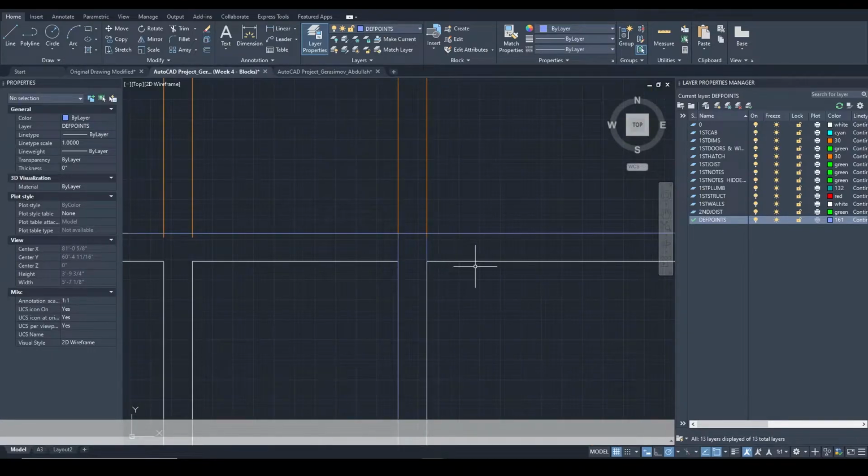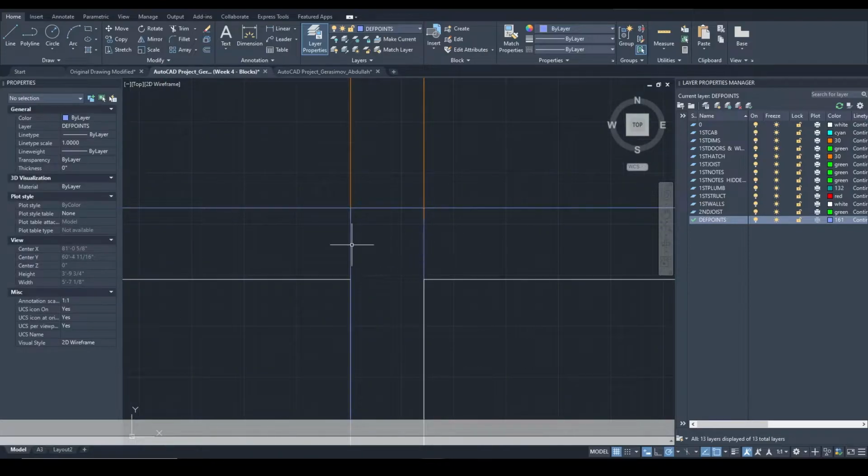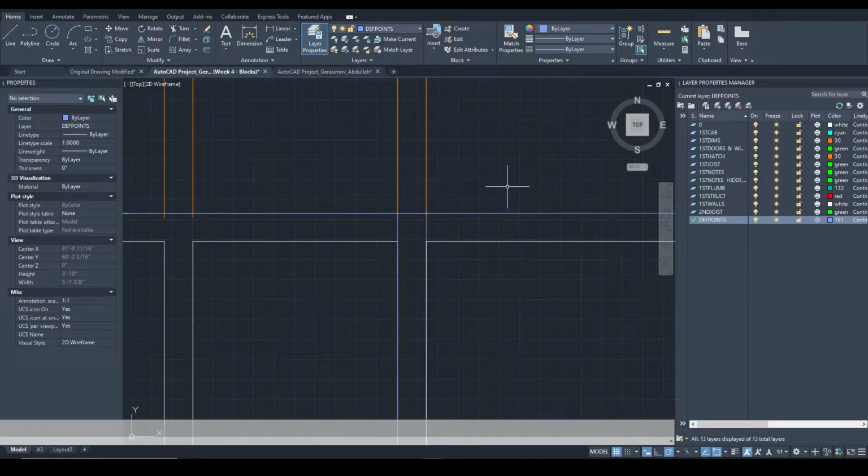Typically when there is a conjunction of the same types of walls, interior walls, you do not want to see these multiple intersections because they're going to confuse people. So the way to eliminate them is, if you have any lines that you can select, you select them. If you don't, you don't have to, but type in TR for trim.